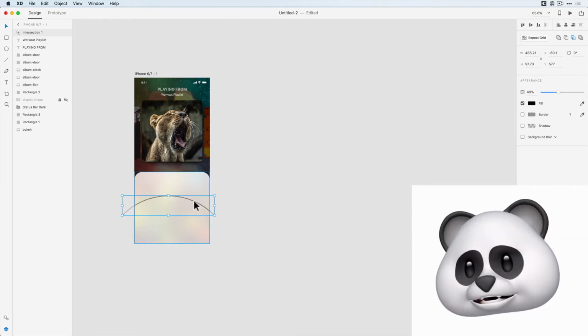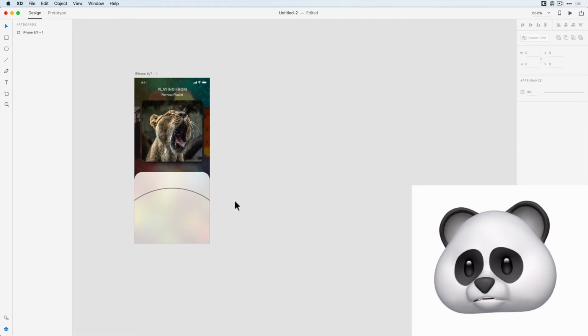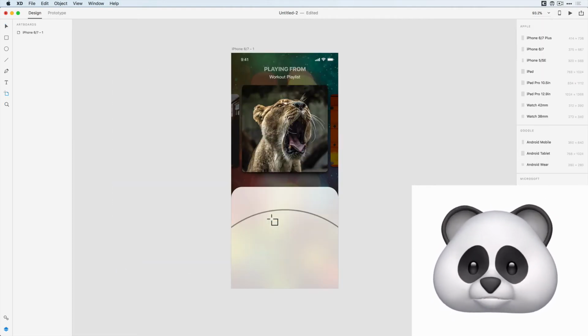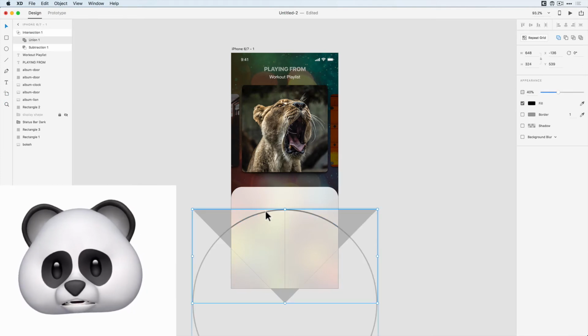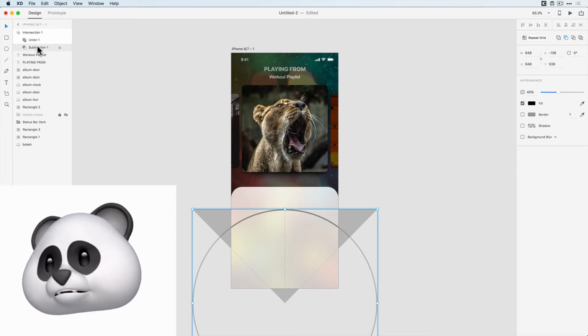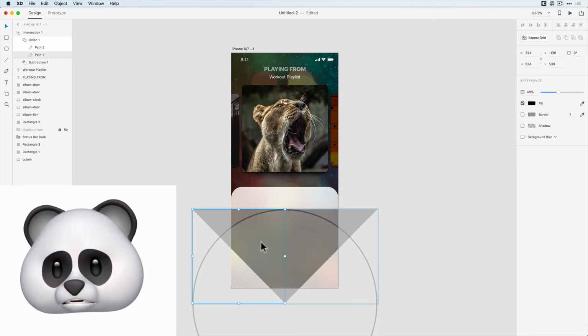We're going to bring this back into the artboard, we're going to center it, and we can see that it goes off the page here. So I'm going to zoom in holding down the Z key, and now I'll double click on this again. And the cool thing is every change that we've made here is non-destructive, so we can still click on any of these elements. And I'm going to double click again until I get to this guy here.